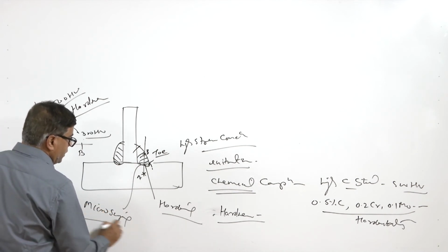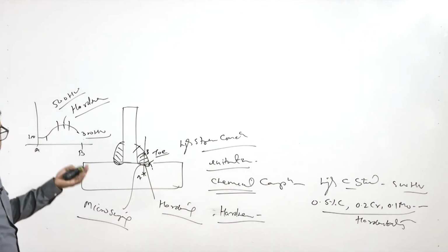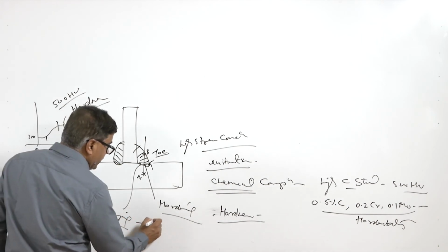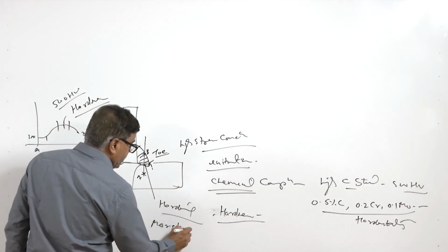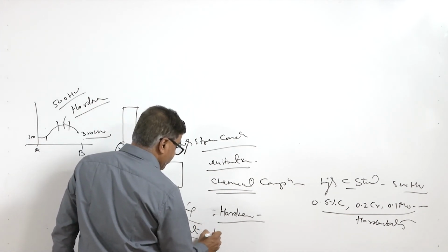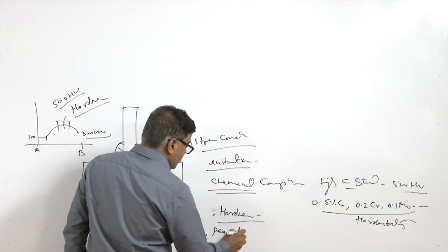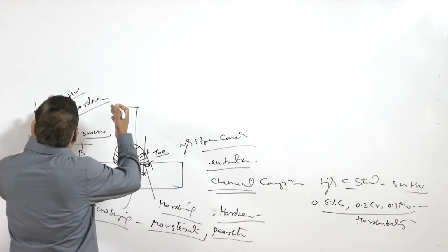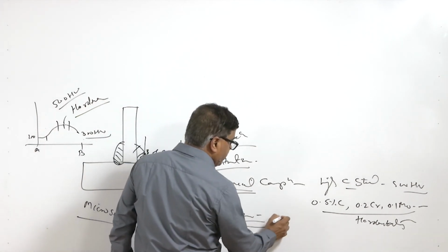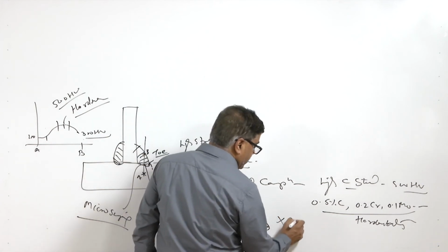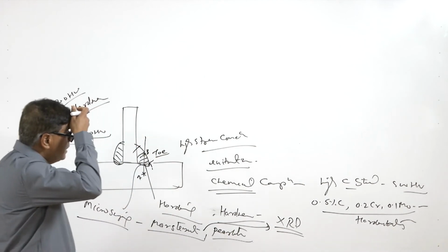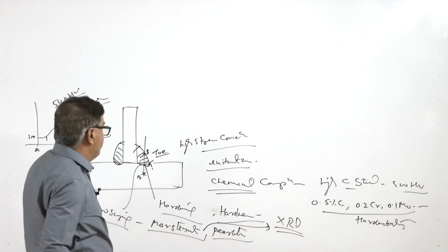of this location where the hardening has taken place, the area which has facilitated the nucleation and growth of the crack. This may indicate the presence of martensite, apart from the pearlite. The presence of martensite will support the hardness results, and if we are still not confident enough about the phases being formed, then we can conduct XRD analysis to confirm if the microstructural transformation has taken place in the heat affected zone.